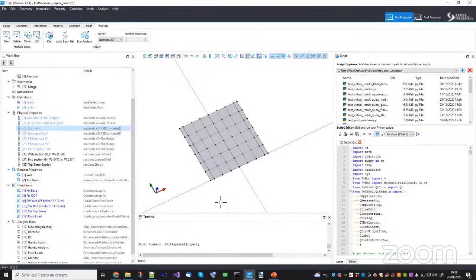Okay. I have another question. So basically, I noticed a very strange behavior. When I use OpenSeesMP for my damaged TC3D model of the masonry wall, with the partition at 4, the result is this. When I change the partition to 5, 6, or 8, sometimes if I use more partitions, the analysis will get stuck or just fail. So I'm curious why it's sensitive to the number of cores I ask for the analysis.